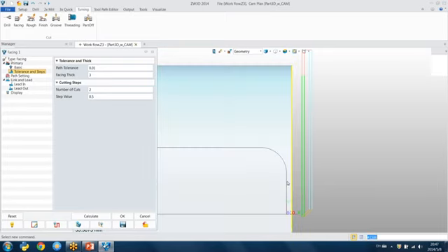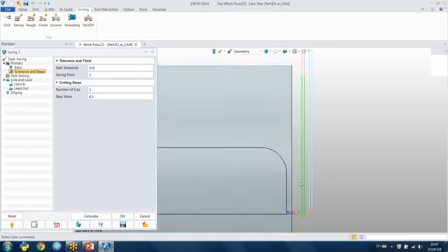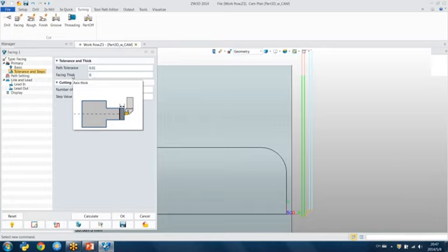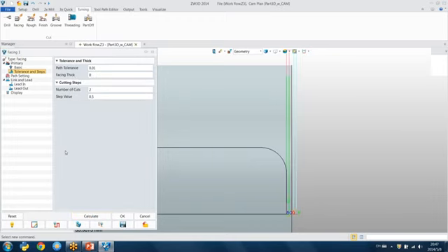Okay. The profile here, but you just need to give in the facing thickness. So you can set the facing thickness to 0. If I put the mouse on the word, it shows me the picture. Okay, the distance of the facing. Calculate.